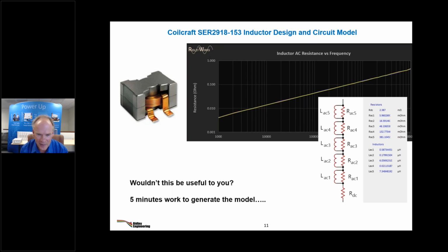So I kind of resist trying to do the gap loss analysis because my philosophy is you shouldn't have any. The gap should not be near the windings because I've seen how severe it gets. Rather than analyzing a poorly designed gap very close to the winding, design a better inductor, move the gap away. And that's what everybody does. You have to do this. You can't have a gap next to the copper. Rudy Severin showed this about 30 years ago. 3 gap lengths away is the rule of thumb.